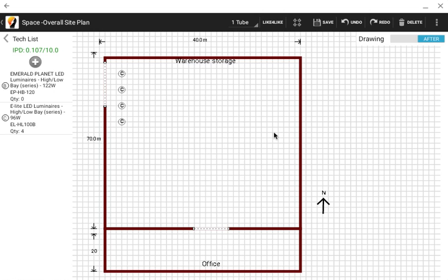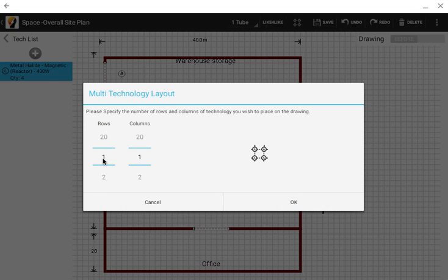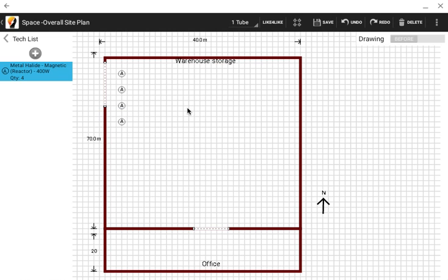Also, if you have a lot of lights, for example, that you want to put on, there is the option to say, alright, I've got 3 rows of 6, and you can choose 3 rows of 6 lights. OK. And now you just click and hold your mouse down and drag it out. So that's a way for you to quickly put on, and you can see it's counting here for you, 22 lamps.